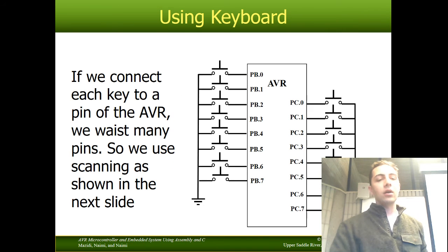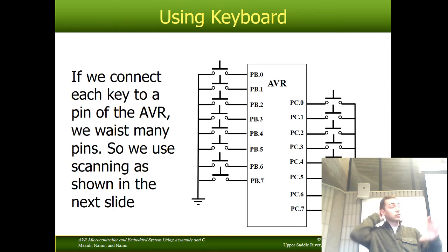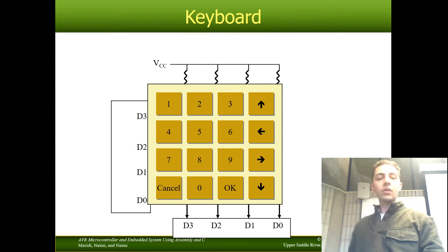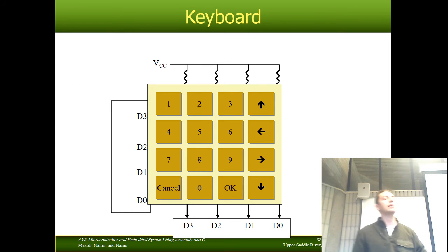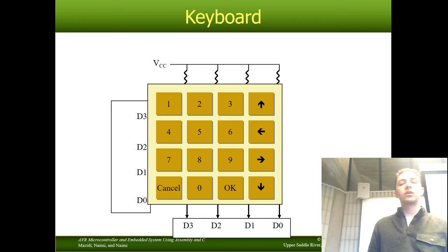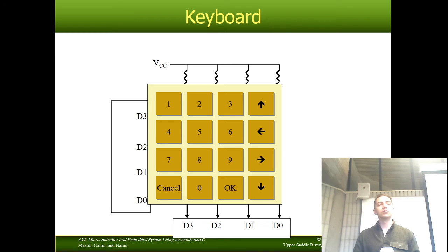All right. Think about debouncing as we're doing this. We'll go through other ways once we get to the keypad matrix. So, yeah, okay, we can do 16 buttons. We've said that. But more often than not, if we buy a keypad matrix, whether it's a membrane keypad, which is kind of those soft feeling buttons, or a keypad like we're going to have, which is just discrete hard buttons, we use a multiplexing routine.